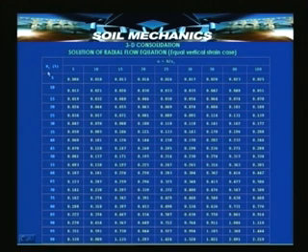Here, for example, if you know UR, for different values of n, you can find out the corresponding TR. Now, what is this n? n is nothing but the ratio of the radius of influence to the radius of the sand drain.